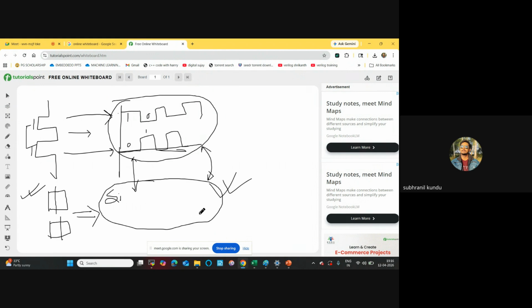We need to maintain the quality of the layout. We need to think about each and everything. Our main job in doing layout is not just to randomly connect and do the placement. Layout is all about the simulation result being matched. That's why we are doing layout, because this layout is going to be fabricated. Fabricated means the chip will be fabricated. This design will not be fabricated; whatever layout we make as layout engineers will be fabricated. So we need to maintain the quality of the layout so that the simulation result and the layout result match.